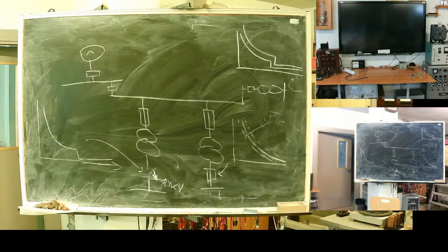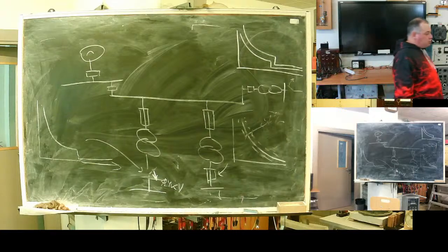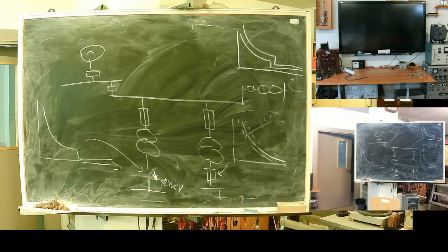If such a fuse burns, net guys do have a very bad habit. They put not what is needed, but what they have with them. Often. Nothing unique. When instead of a 25 amp fuse, you will find 250. Because they just had it with them.